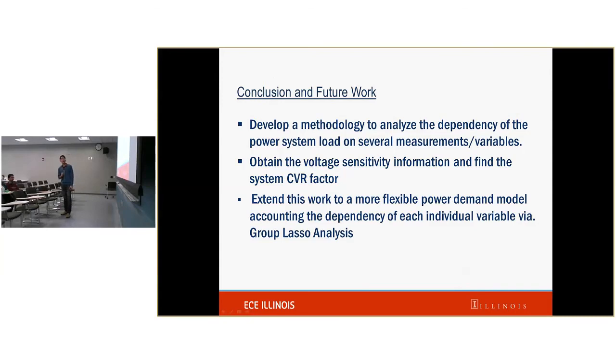So the conclusion for this talk is that we developed a methodology to analyze the dependency of the power system load on several measurements and variables. The measurements include the day of the week, hour of the day, season, temperature, and voltage. We obtain the voltage sensitivity information, and we use that voltage sensitivity information to find the CVR factor.